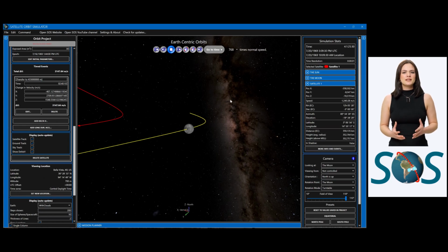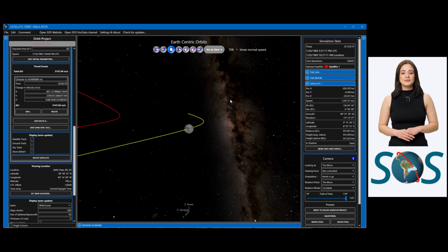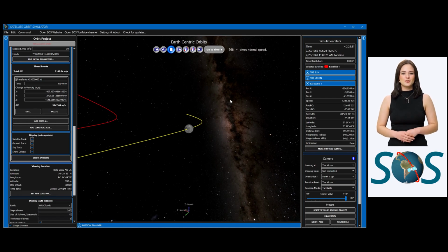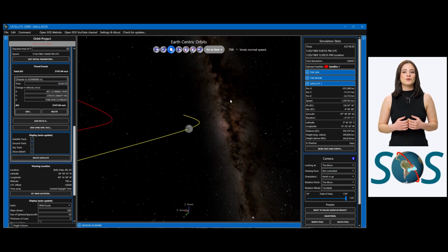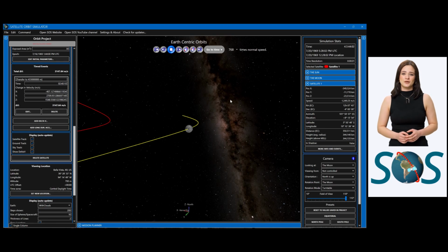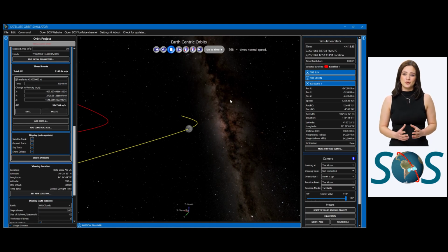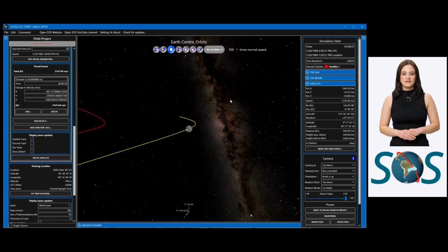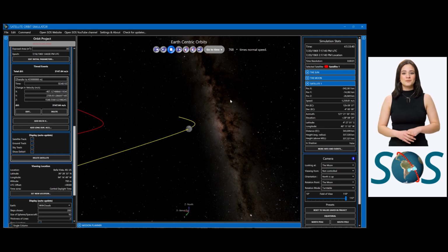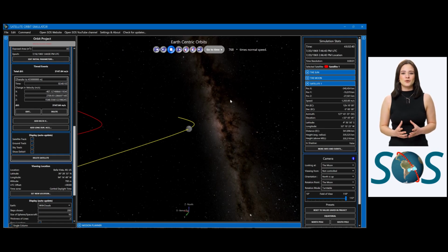4. The spacecraft passed ahead of the Moon. This was to ensure that, if the lunar orbit injection rocket failed, the spacecraft would use lunar gravity assist to return to Earth. 5. The lunar orbit injection burn occurred behind the Moon and was opposite the velocity. In other words, it was used to slow the spacecraft so it would enter a lunar orbit.